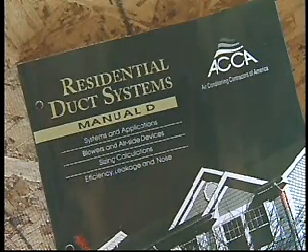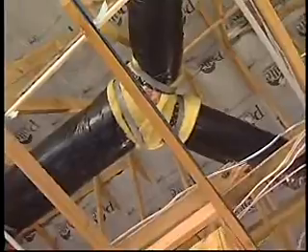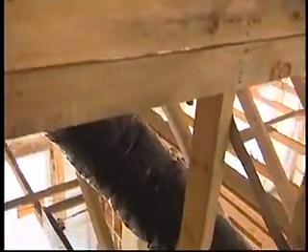Since most homes built today are production homes, what are your recommendations for working with flex duct? Well, the most important thing with the flex duct, first of all, is that you design the system to use it. You don't design it like it's metal and then put in flex duct. So you design it right, then you put it in right. So you have nice sweeping bends, you don't crinkle it, you don't shove it down in a wall space to go down to the basement. You don't do any of those kinds of things.